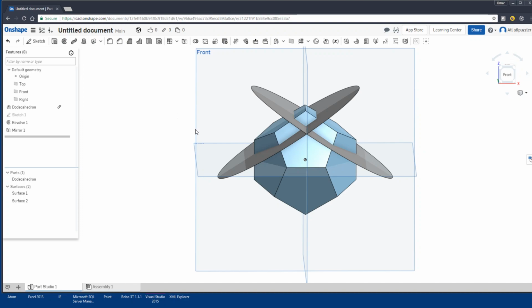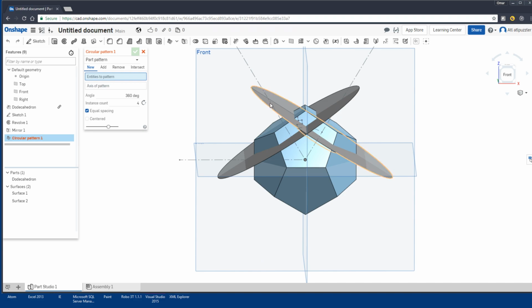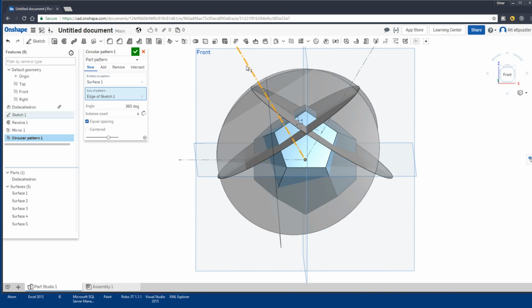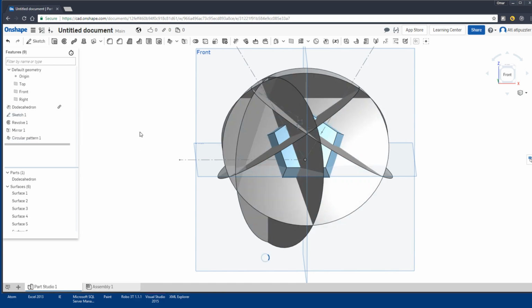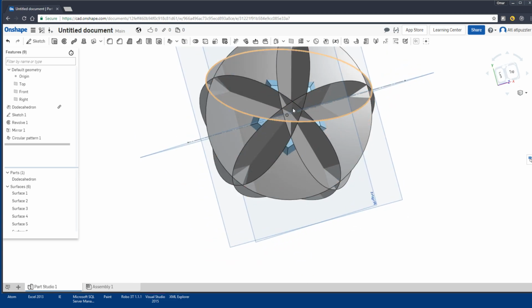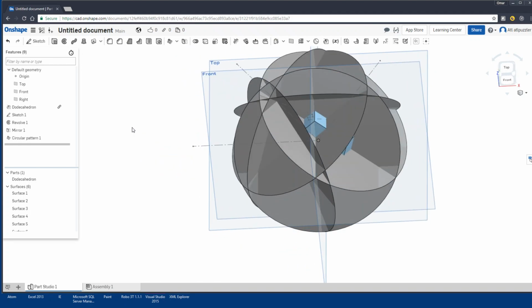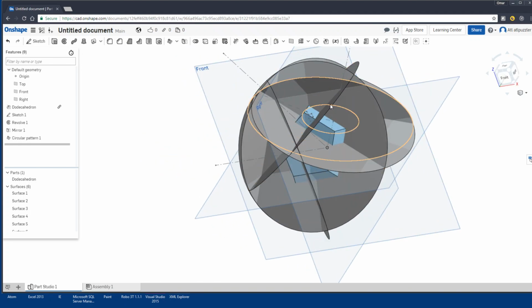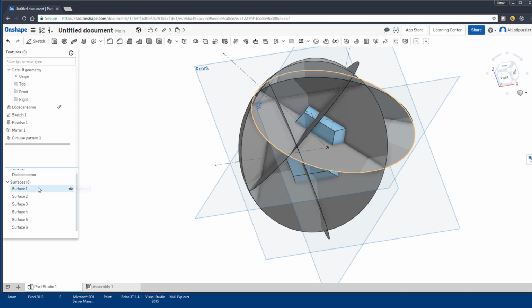and finally you want to take the circular pattern and take the initial disk and rotate it around this other axis 5 times. And this is what you get. You get something that looks like a star, and under the star there's a 6th surface that will cut it. Okay, and here's the 6 surfaces.